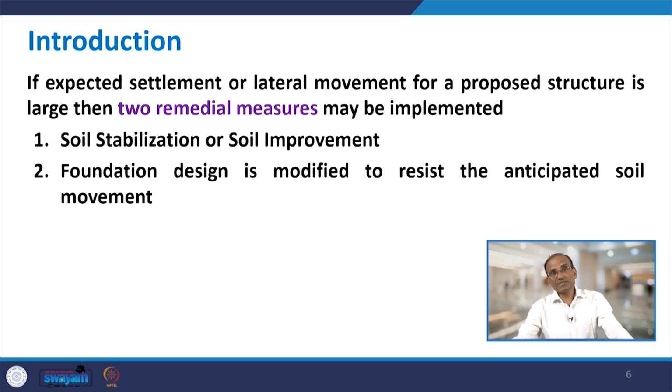Coming to the introduction part, if the expected settlement, or we say lateral movement, for a proposed structure is large, then 2 remedial measures may be implemented. This happens most of the time, that either settlement or lateral movement are not within the permissible limit, particularly when you consider earthquake loading. This is the common problem when the soils are subjected to earthquake loading. Then you may have 2 alternatives. One is that soil stabilization, or soil improvement, or we say ground improvement techniques are required.